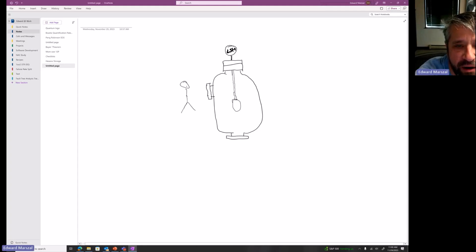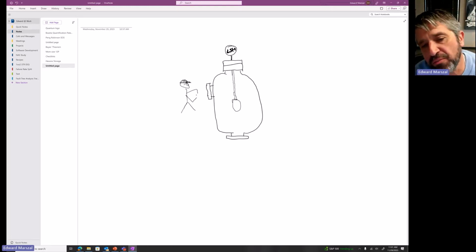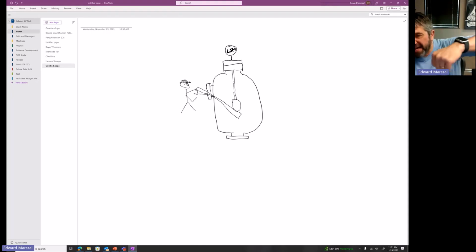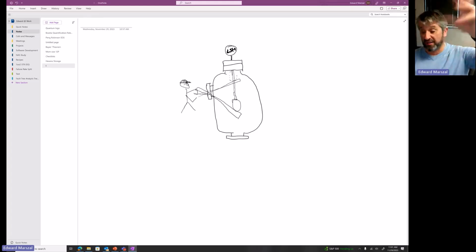I've got my hard hat and safety glasses, so everything's cool. I'll be perfectly safe. And what I'm going to do is manipulate... actually, I drew this poorly. Let me draw it so that it'll actually work. So I'm going to manipulate my precisely calibrated 2x4, stick that into the manway, and lift that float up until it reaches the trip point. And when it does, the level switch activates and everything's good.